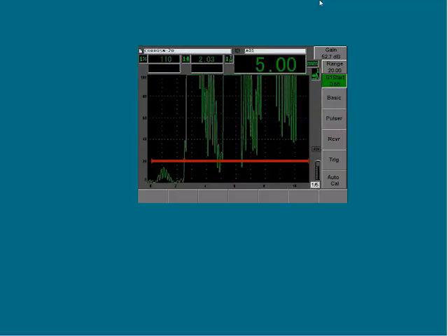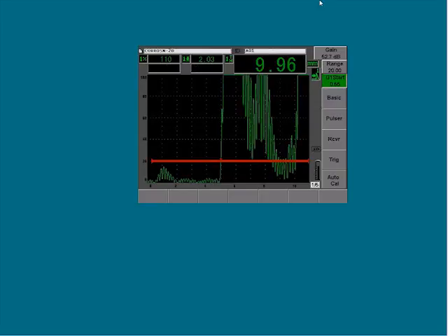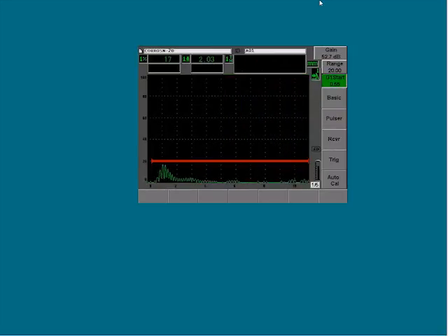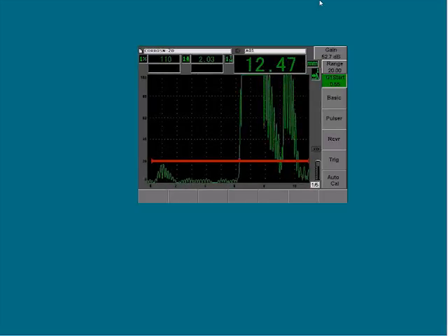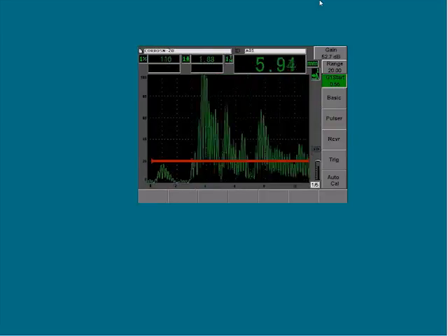But one of the reasons that I may have some inaccuracy on something like this step, where I'm 0.04 millimeters away from my target, could actually be just the signal height and the position at which I'm making the measurement on the leading edge of this signal. But I think certainly you can see that this took maybe a couple of minutes to set up, and as I go across the sample here, I have a sample with actual corrosion.